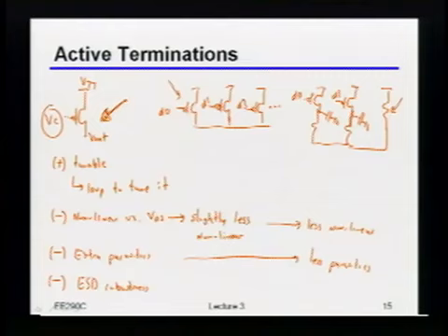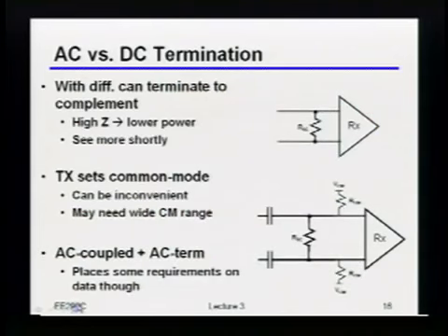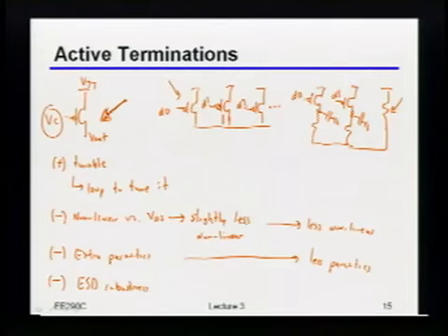Okay, great. So unless there are more questions on that, there's one other quick thing I would want to mention in this context, which is related to a question that Stephen asked before. If I really move to differential signaling, there's one simple trick I can play, which we'll hopefully see today, and if not, next time, that can get you a slightly, in fact perhaps even fairly substantially, improved efficiency from the standpoint of signaling power. Okay? So the trick you can play here is, so far I've mostly been showing these things as being terminated in a single-ended way. Right? So I've always been putting 50 ohms to the equivalent of ground. Right?